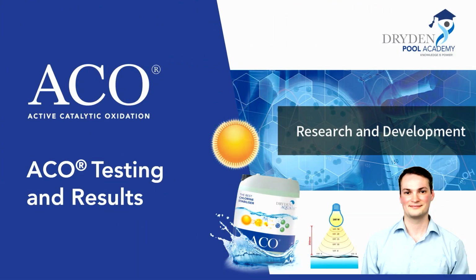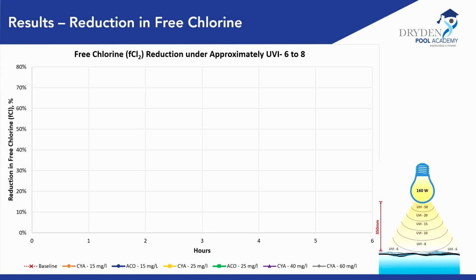Okay, so up are the actual results. So what did you test here again? If we show the graph, we've got the reduction in free chlorine when exposed to a UVI of between 6 and 8. On the left-hand axis is the reduction in free chlorine, and on the bottom axis is the duration. So I go from 0 to 6 hours.